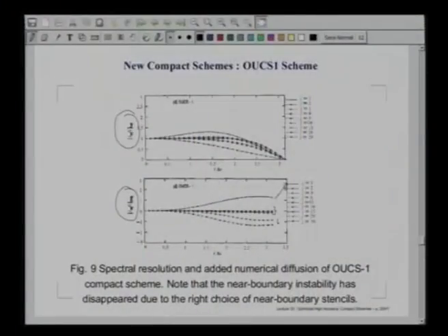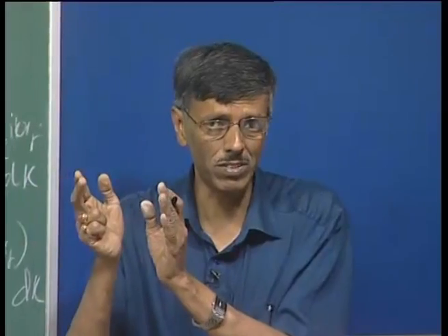These large values that you are getting are near the outflow boundary, and at the outflow boundary what do you want? Most of the time in computing you are getting the propagation of disturbances, and if you do not set the outflow boundary condition properly, they actually reflect from the outflow boundary and distort the solution. So, we want to avoid that.